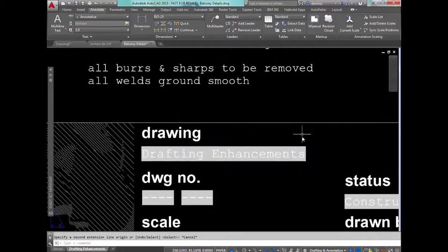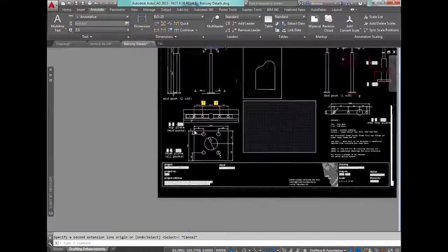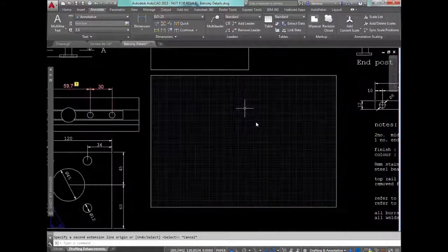Another thing is for the isometric. For the isometric, what we normally do is type in a command or reconfigure it for us to be able to change the view. But for AutoCAD 2015, isometric drawing is just a click away. It introduced an icon available here in the status bar. With just a click away, we can change our view.